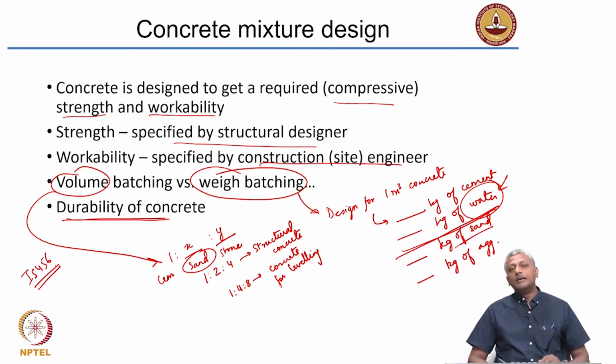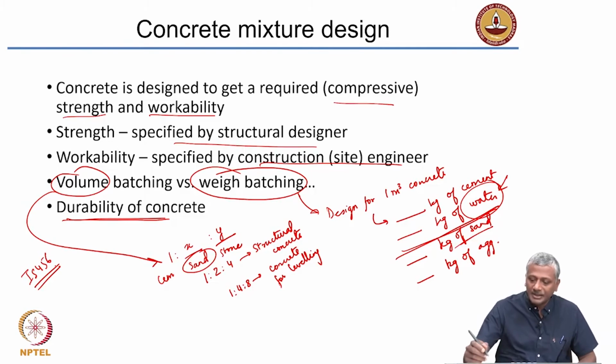But today increasingly people have realized that it is the durability of concrete and the associated aspects that come with it which govern the performance of the structure much more than the strength. In most cases, strength is not really a consideration because we usually over design the structure with respect to strength. But with respect to durability, if we don't have a clear understanding of the environment and what can happen in that environment, we could be in for a lot of problems with respect to the concrete structure. So, today increasingly the focus is shifted to durability, and because of this there is one more additional person that needs to come in for large projects, and that is a concrete technologist.